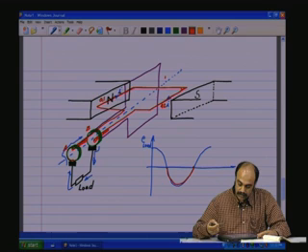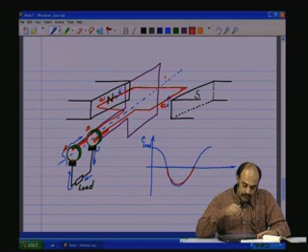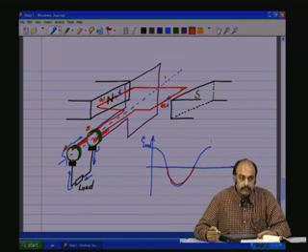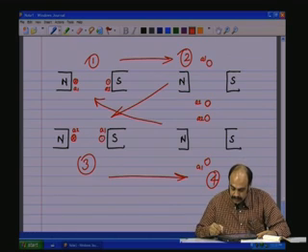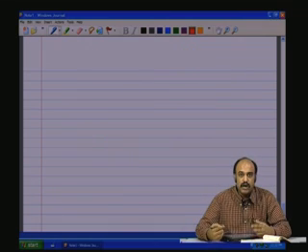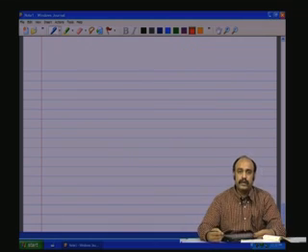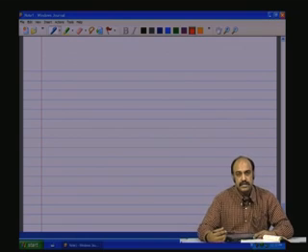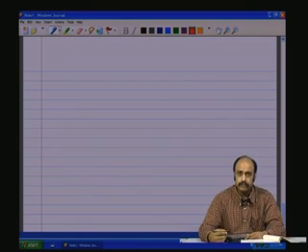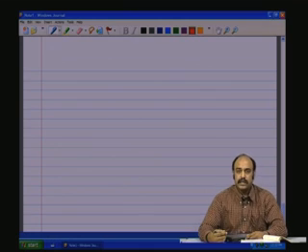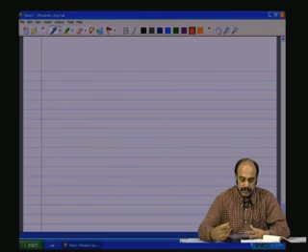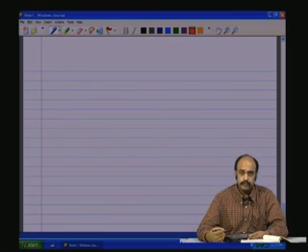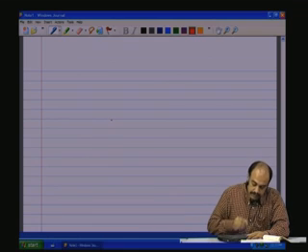So, what we have here is a generator, but it generates an AC waveform. How do we generate a DC waveform from this? Means, how do we rectify it? If we pass it through a rectifier, we get a DC from the AC induced voltage. But we are not going to build the rectifier using diodes, but it will be built in along with the motor here. So, let us make a slight modification in the way the motor is built.